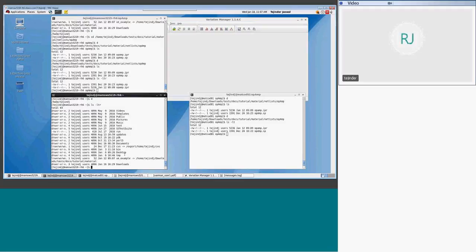Those parameters are already statistically defined there, how the variation of different parameters is defined in the length, width, and so on. Basically, they look at those with Gaussian and other types, and on top you can define temperature and different corners you want. So it takes that into consideration, and the algorithm does that intelligently.